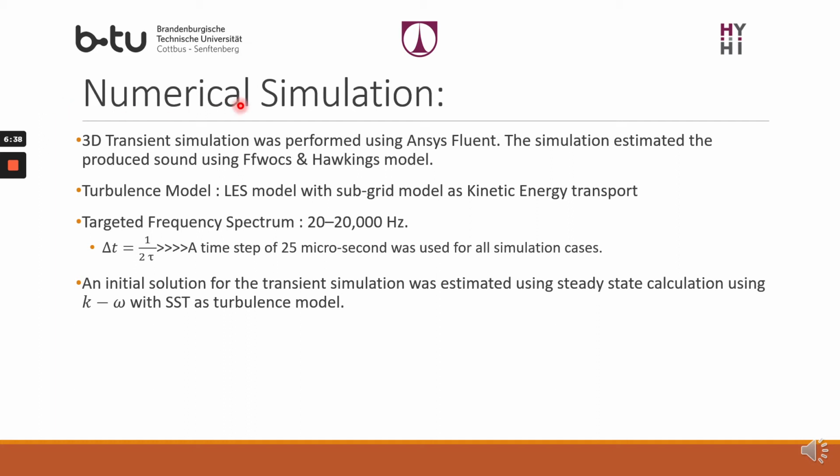Numerical simulation has been carried out as a 3D transient simulation. It was performed using ANSYS Fluent software, and it used the model of Ffowcs Williams and Hawkins in order to estimate the acoustic sources. It used a turbulence model of large eddy simulation with a subgrid model of kinetic energy transport. Moreover, it targeted the whole acoustic frequency spectrum from 20 Hz up to 20 kHz, and therefore it used a time step of 25 microseconds that was calculated according to this equation.